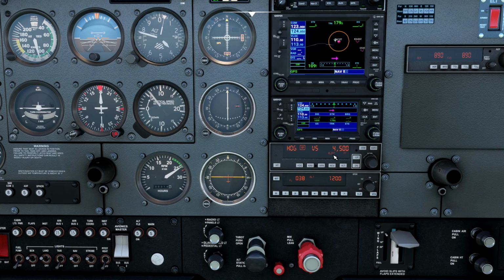The altitude alerter comes on 1,000 feet prior to the selected altitude, so pretty much came on immediately after I initiated the climb, since I was within 1,000 feet. And then that'll go off at 200 feet prior to level off. So we just keep an eye on the airplane, make sure that it's doing what it's supposed to. Keep an eye on your speed to make sure that you're not asking too much in the vertical speed department, and then it will automatically capture when it gets to 4,500 feet.